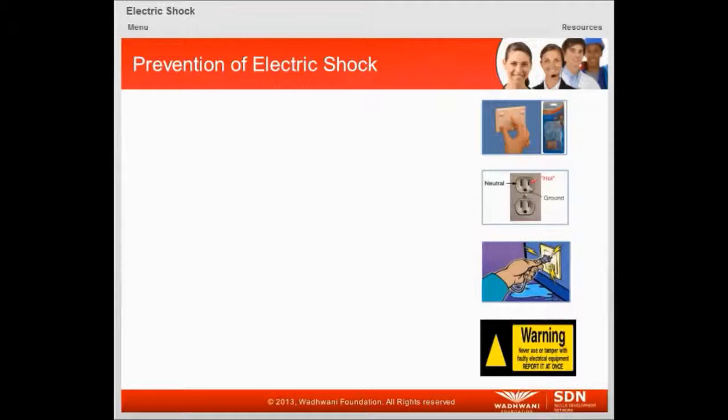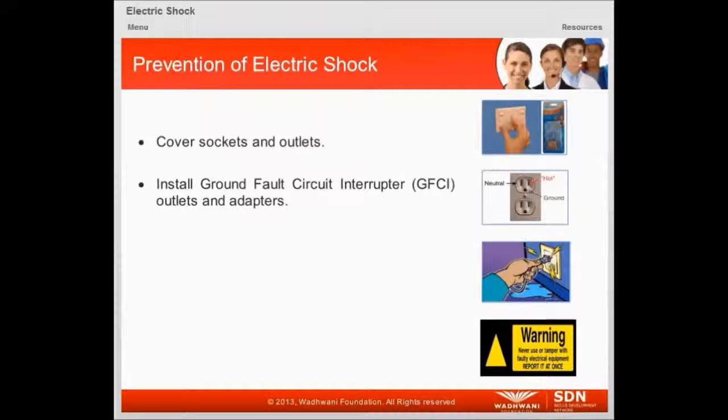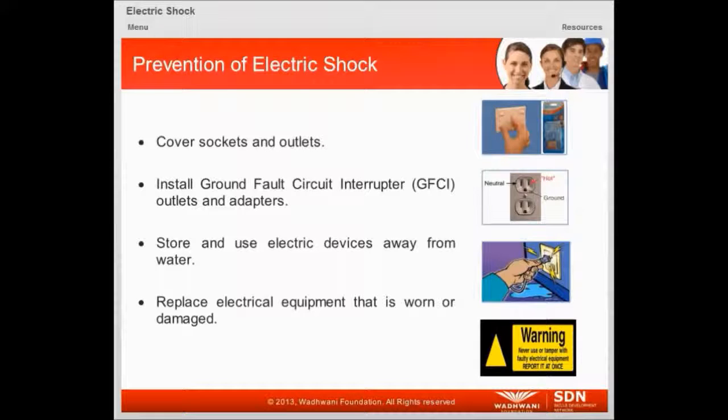Now let us see how we can prevent electric shocks. Cover sockets and outlets. Install ground fault circuit interrupter GFCI outlets and adapters. Store and use electric devices away from water. Replace electrical equipment that is worn or damaged.